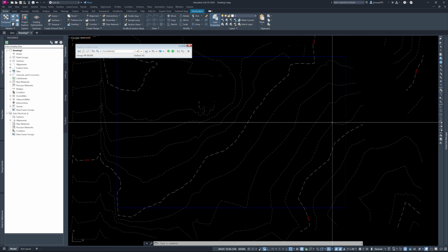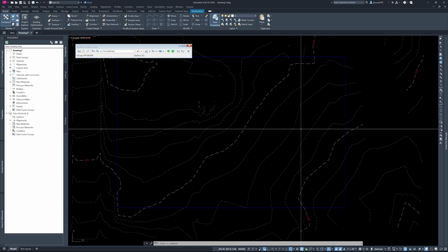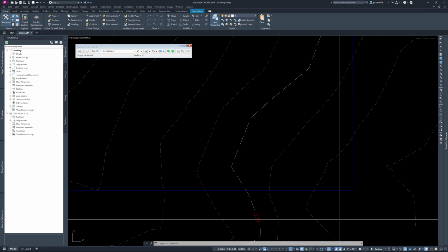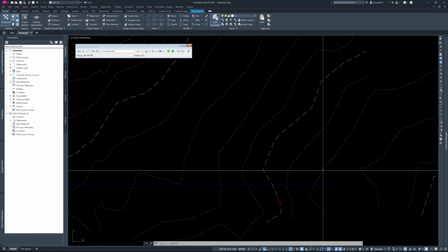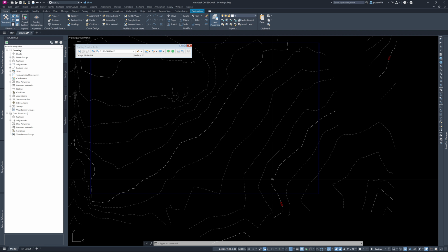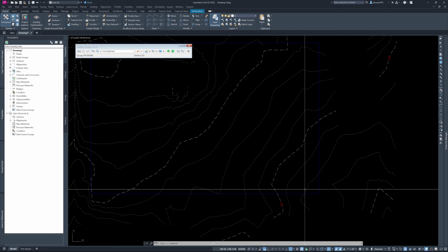So we need to have an existing surface in Civil 3D. And then what we also want to try to do is estimate the top elevation of the proposed basin berm. Well, we can look at here. Our elevation is 1220 there, so that means that's 1228. So we need to be higher than that. So let's say if we have 3 or 4 feet above this elevation, we should be pretty good for the basin top.